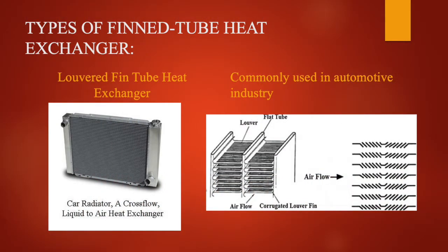Pictured here is a louvered fin tube heat exchanger, also known as an interrupted surface fin heat exchanger. Interrupted surfaces achieve heat transfer enhancement by the continuous growth and destruction of laminar boundary layers on the interrupted portion of the geometry. One of the most used examples of the interrupted surface is the louvered fin. Louvered fins gained popularity in the 1950s, and that has been maintained today. Today, louvered fins are popular in automotive, heating, cooling, air conditioning, power plants, and the food industry. Pictured is a typical structure of the louvered fin.